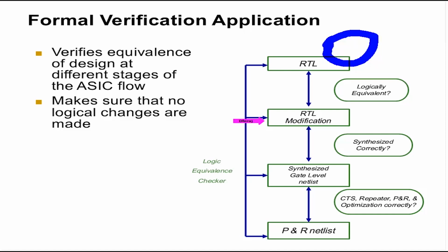This is not to verify whether the synthesis tool has problems. Although, yes, in some cases the synthesis tool might have a bug, and you might discover this bug during formality. But the idea here is to make sure that your synthesis constraints are correct. What if by mistake you set a logic 0 on an input port? If you set logic 0 on an input port, DC will optimize all the logic related to whatever that input port is driving. DC will remove that logic completely, and now you can discover such problems in formality.